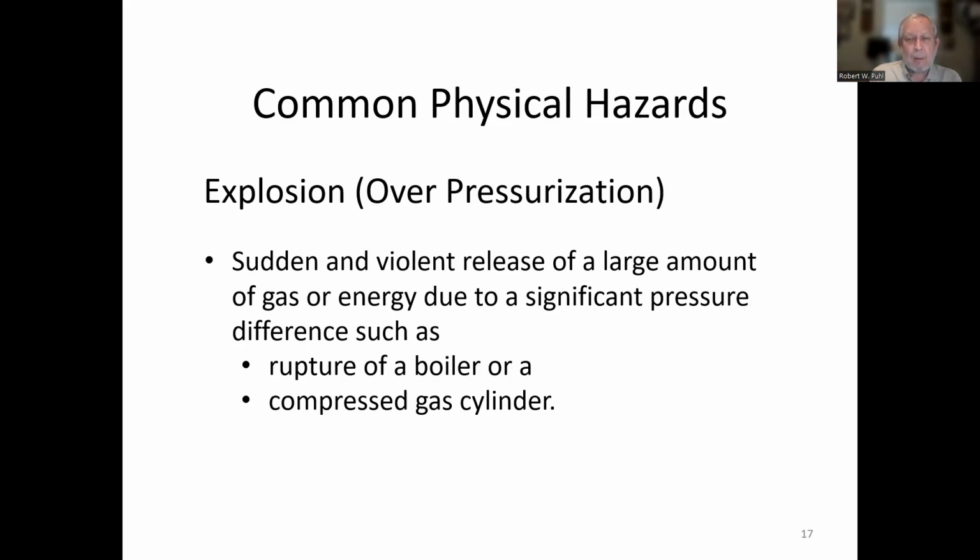And I used to go around with the guy that did that, and some guys after they switched companies, switched carriers, and it was interesting. They would check every pressure vessel we had, not just boilers. They were called boiler inspectors, and we had a lot of pressure vessels with ammonia in them, or they could be just air compressors. Every one of them has a MAWP, maximum allowed working pressure, and has a pressure relief valve. And they would make sure that the pressure relief valve was set to go off at no higher than the maximum allowable working pressure.